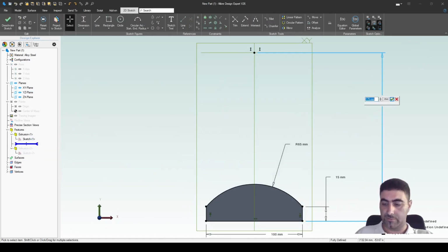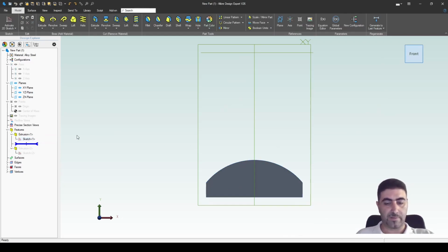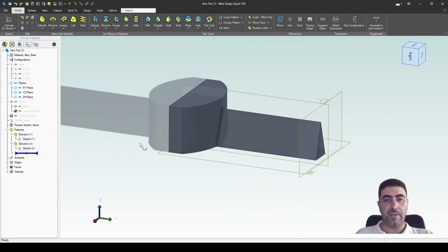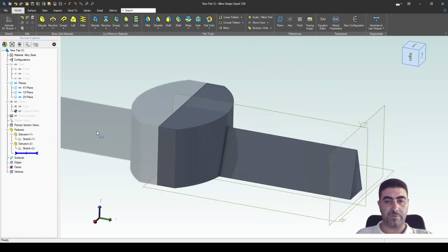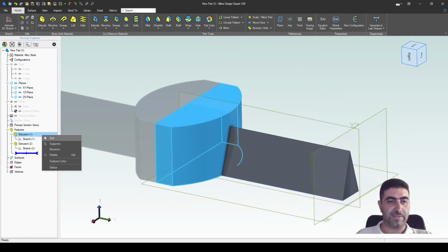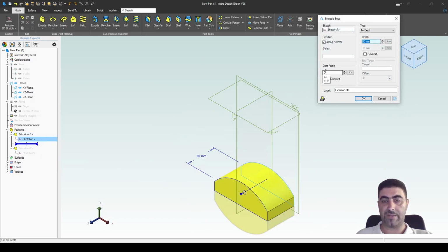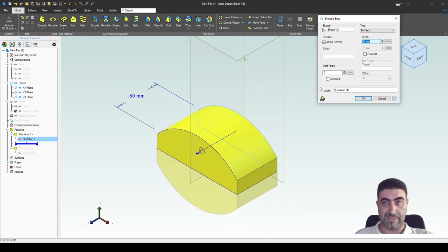Let's just bring this back into position. Generate to last. Finally, let me talk about another very important option of the extrude command. Let's do it here, which is the draft angle. Okay. Now this is extremely useful when we're making molds for plastic injection, and that's why the terminology is borrowed from injection molding manufacturing method. Okay. And then in injection molding, a standard angle that we might need for a good ejection of the finished part of the mold is 5 degrees.